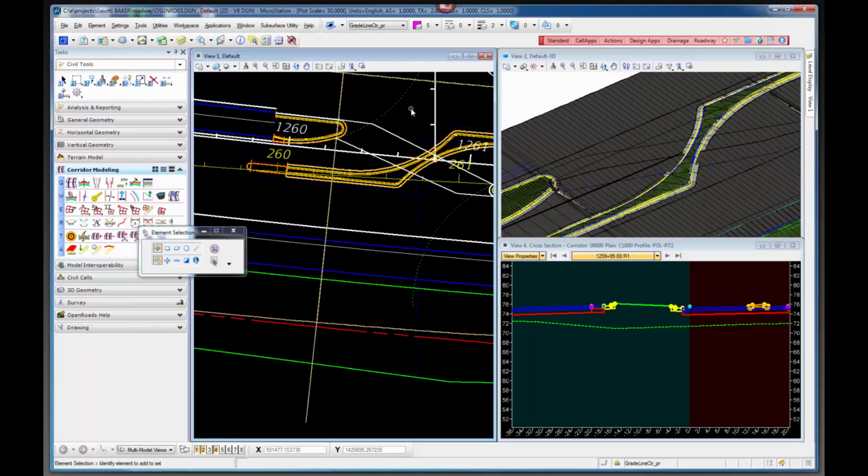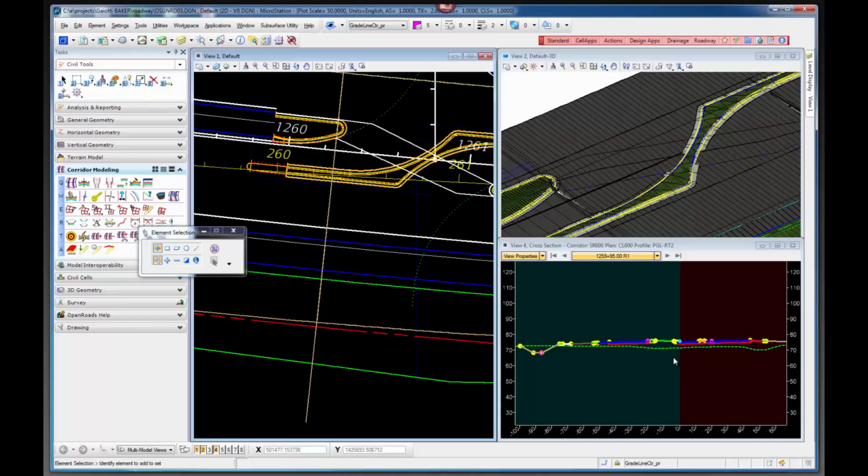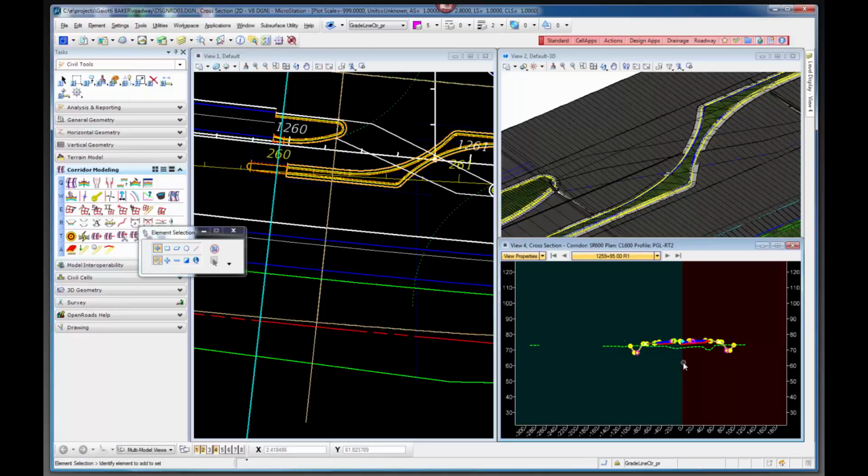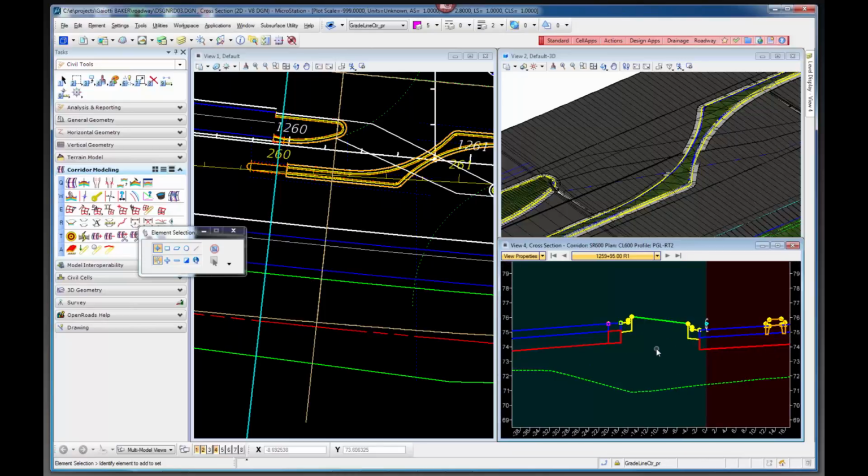So these are some of the techniques we've developed for building the crossover details. Number one, it gives you a realistic model and gives you the ability to not have to draw in that information by hand in cross sections, which obviously we don't recommend. If you wanted to modify this slope in the middle, you could just add a break line across the middle of this line here and then profile it in order to make that work.